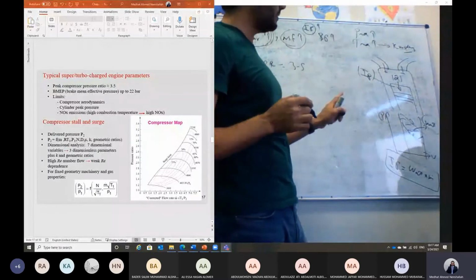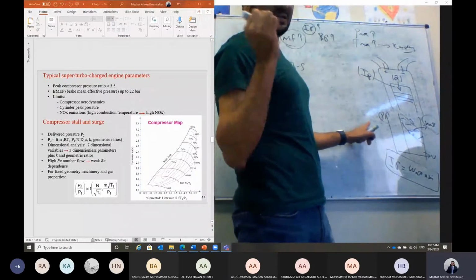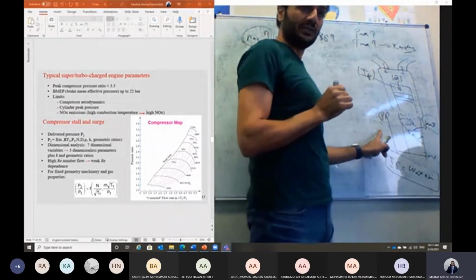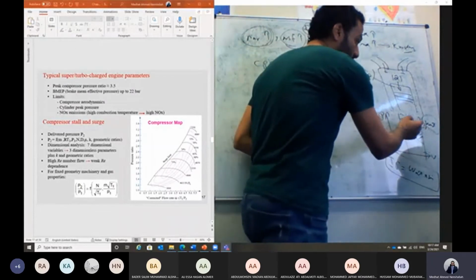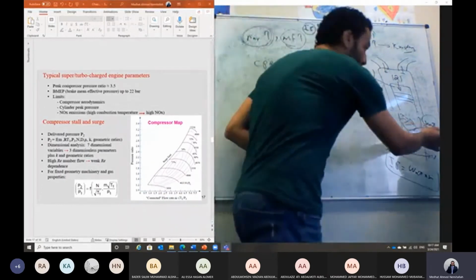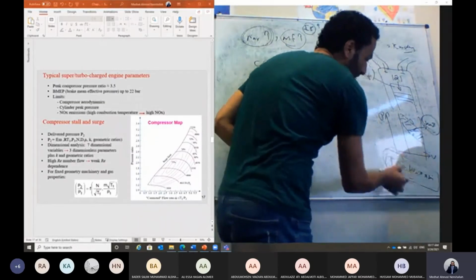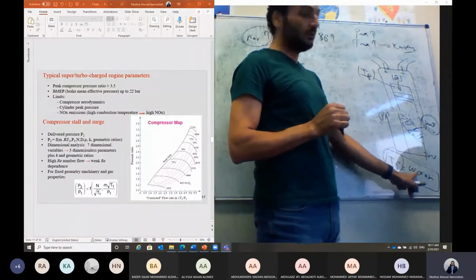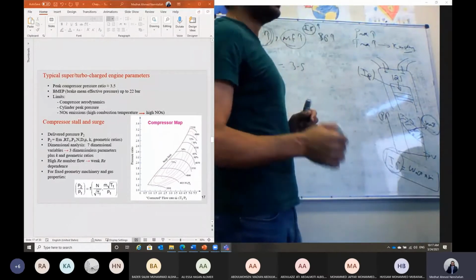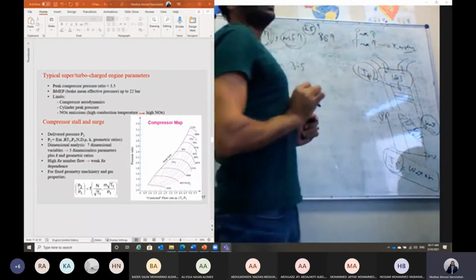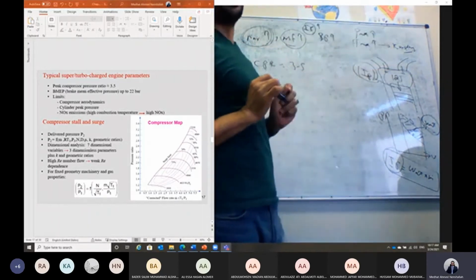As we said in the last chapter, for the engine cycle, we have drawn the PV diagram, and the net work is represented by the area contained by the cycle. This net work we call the indicated work. Indicated power is equal to the indicated specific work multiplied by the mass flow rate. So the indicated power is the power generated inside the cylinder, which pushes the piston down.